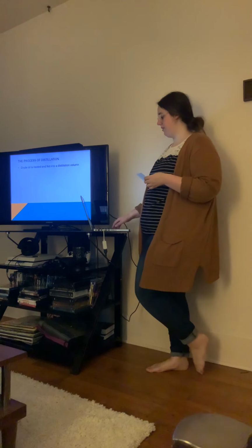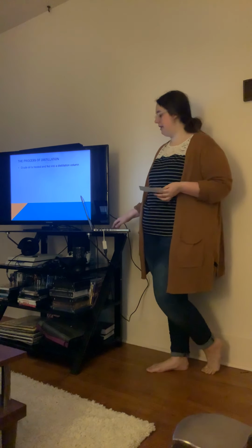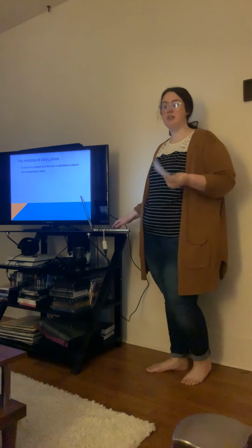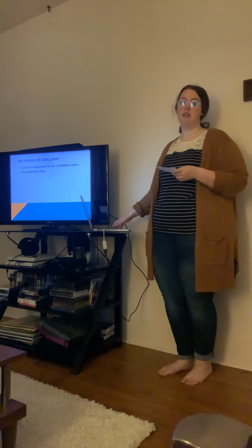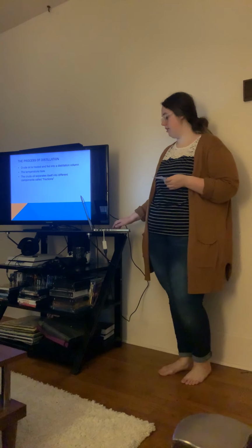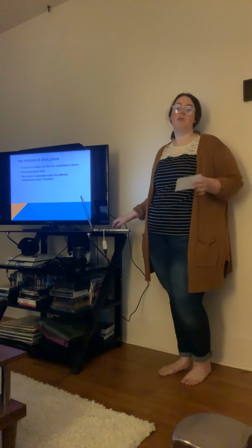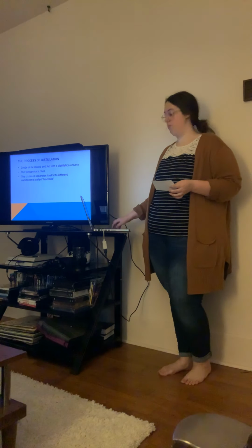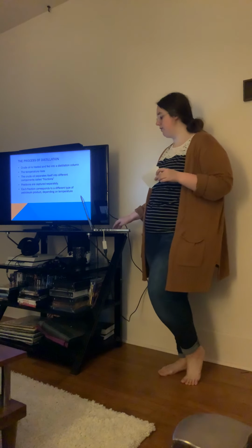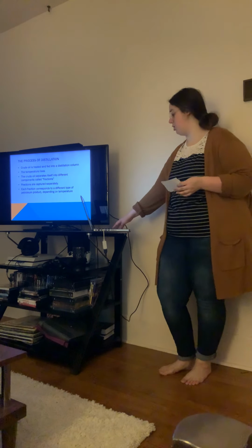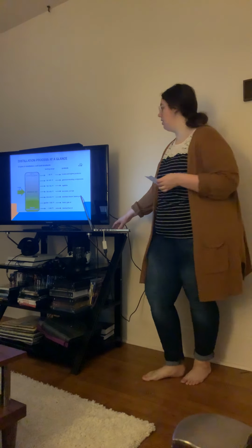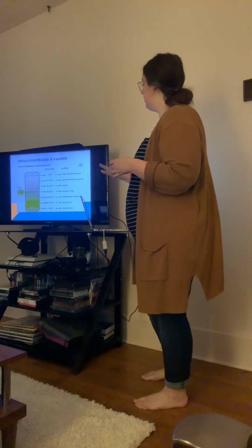The process of distillation is that crude oil is heated and then fed into a distillation column. After that, the temperature starts to rise depending on the product that it is being turned into, and then the crude oil separates itself into different components called fractions. So there are different tubes that it goes into pertaining to whatever is being reformed. And then the fractions are captured separately, and each fraction corresponds to a different type of petroleum product depending on the temperature. So the next slide is actually going to show you kind of an example of what a distillation unit does. So the crude oil distillation unit and products.